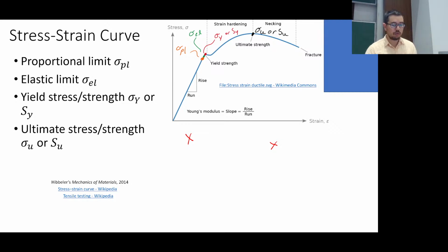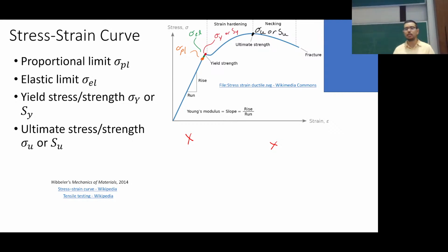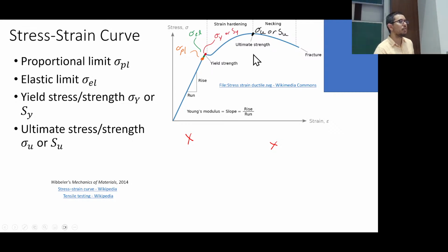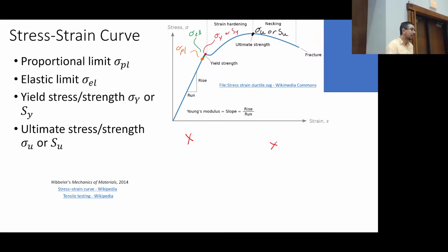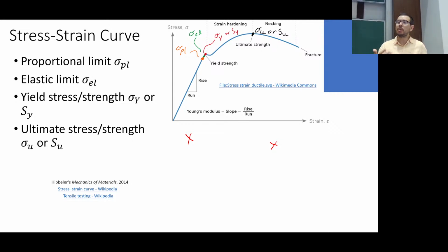Elastic modulus, for example, first. Up here, this is the ultimate strength. Do not design your product for its ultimate strength unless it's a one-shot type of thing, or you're actually doing fatigue calculations. For fatigue calculations in Design of Mechanical Components 342, you'll get a better understanding of what it means for a material to experience cyclic loading, but we won't cover that here. And there's a fracture stress, which is the stress when it finally fails.